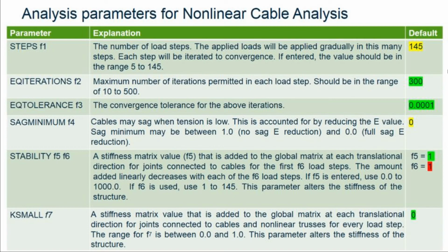The default value is 0, which I again put in yellow color because this default value is not good. Many times we have to change this. Okay, so that is the most important parameter, sag minimum, to take into account the stiffness of the sagged cable member.